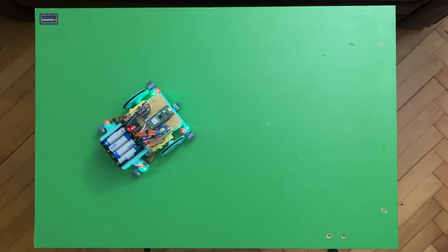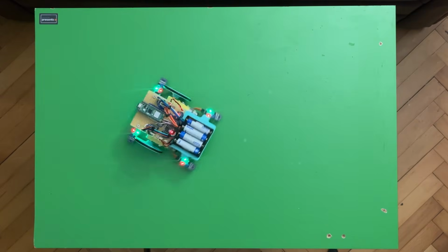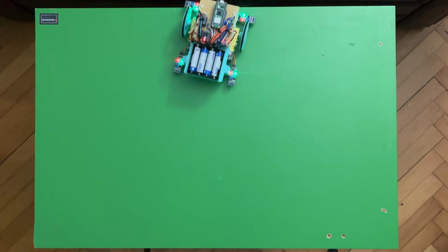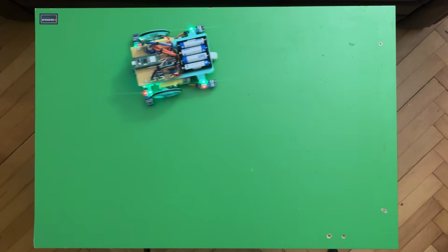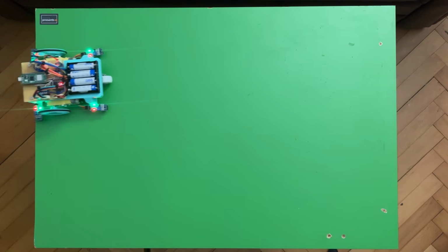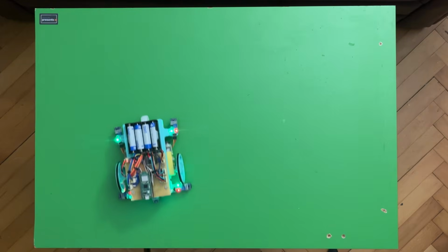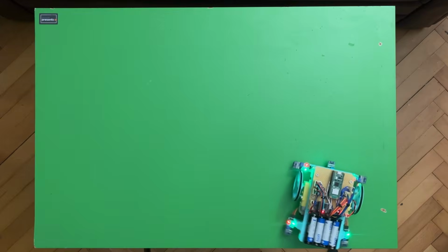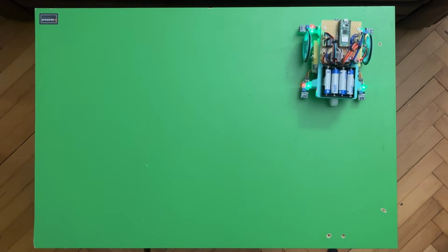So yeah, the robot is pretty easy to drive around. I'm just using my keyboard, and also you can see on the screen how the robot is tracking where it thinks it's actually going. But to be fair, there's of course gonna be some errors because we are only here calculating where it is based on the encoder positions. So it's not perfectly accurate, but it's better than nothing. So yeah, our little robot is doing great, and it won't let us just drive off the cliff.